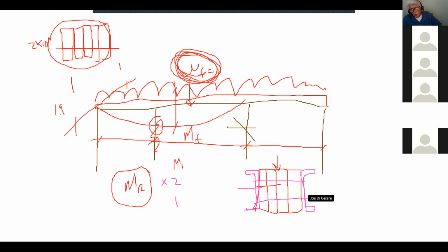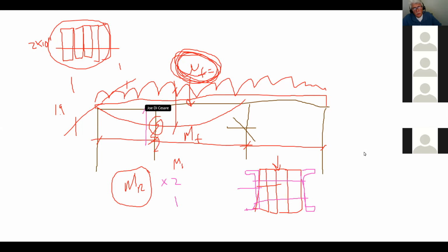And what I do strongly recommend, if you're going to do this, is that before you do anything here, you jack up the column. You jack up the column at least 1/8 of an inch above its original position, so that when you put all the steel reinforcement and you release the thing, the wood will then work with the steel together. If you don't do that, it's not going to happen.